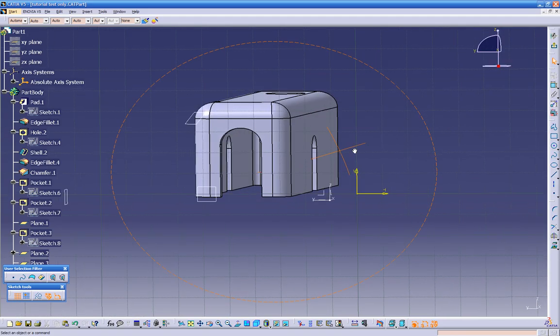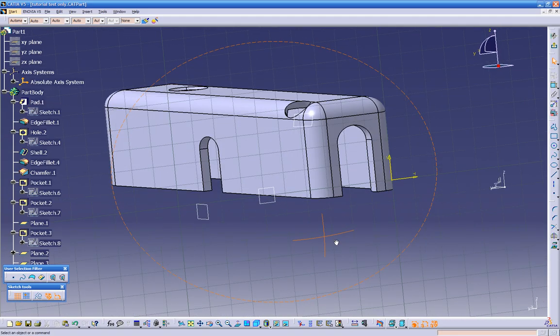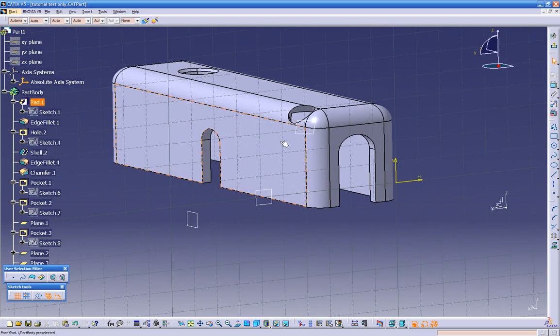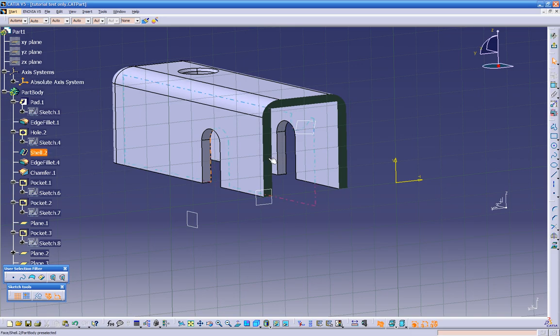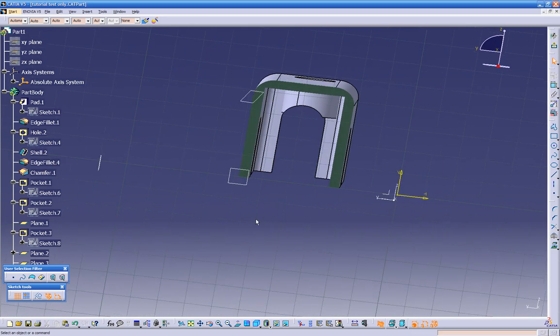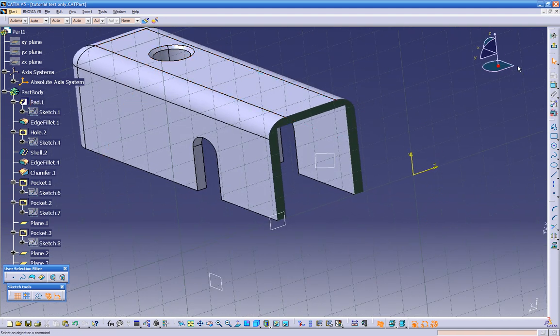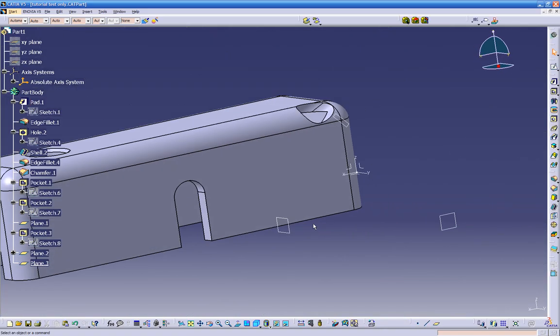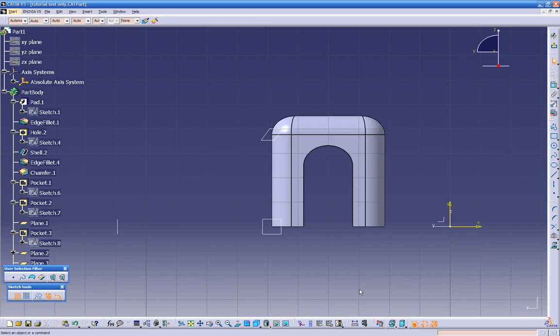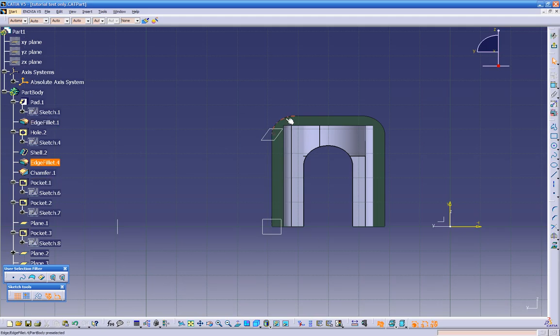Okay, so right now we're working on this sketch right here, but you cannot see what's going on. So what we can do, if you click on this option right here, see what it did? We can see up to that plane the geometry, but that doesn't mean it's cutting up the geometry. If we get out of the sketch, it's just a construction element. So let's go back on the sketch and we click on the cut part by sketch plane. So we can see our thickness.